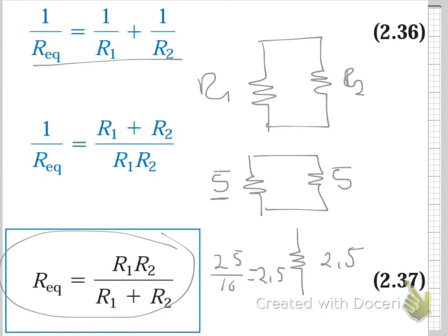This is a quick tip for when you're in the middle of something, things are getting rough, and you're running out of time. Then you just see 2 resistors in parallel that are equal to each other. Just remember that the equivalent resistance is equal to half.